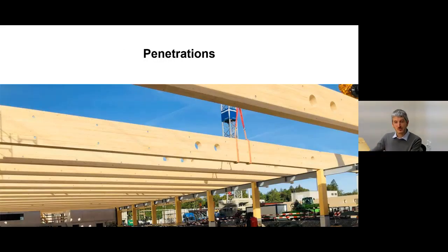Now, this was a quick run through the notches and how you can determine the demand and how you can design for your reinforcing. I'm gonna pass on to the next topic, which are penetrations. Now, even more critical than notches, because notches normally you can prevent, you know them potentially during design already. Penetrations normally occur once you're on site and you have designed your 500D beam for 80–90% of use, and then the services guys come in and want to drill a 400 mil big hole through it. That obviously doesn't work with timber, and there's some very strict parameters you need to consider, and therefore that's something which normally should be coordinated long before beams go on site.